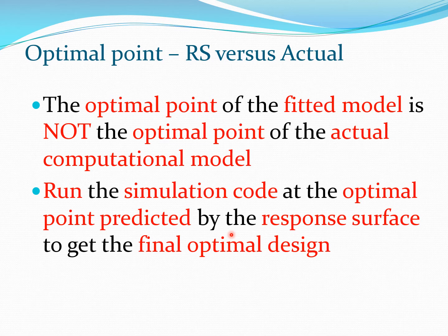So this is something which is very important to remember, that the response surface is being used only as a guide. You run the simulation code at the optimal point predicted by the response surface to get the final optimal design. And therefore, if people have issues regarding your response surface, your fit, your functions, your designs taken, and so on, all this can be resolved if you get a good solution at the end of this process in terms of the final simulation code. So you're not relying on your response surface for the end result. You're only using the response surface to guide your path.